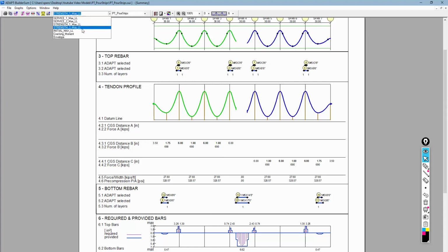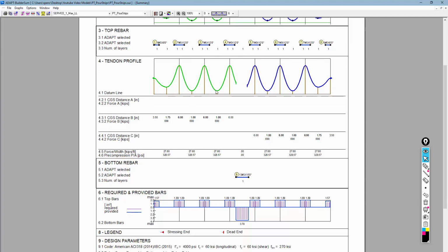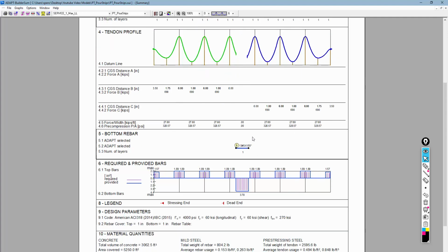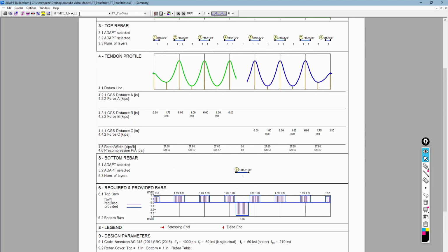And then for minimum reinforcement, you can see this is really based on post-tensioning two-way slab prescriptive reinforcement here at the bottom, because the stress level may be low enough in this particular condition. We don't need any reinforcement at the bottom in these other spans, except for here again, this is an RC span, so we need essentially minimum temperature steel, shrinkage steel for this location. And this should equal, for example, 0.0018 times area gross for example, for ACI code. This is being designed at ACI 318.